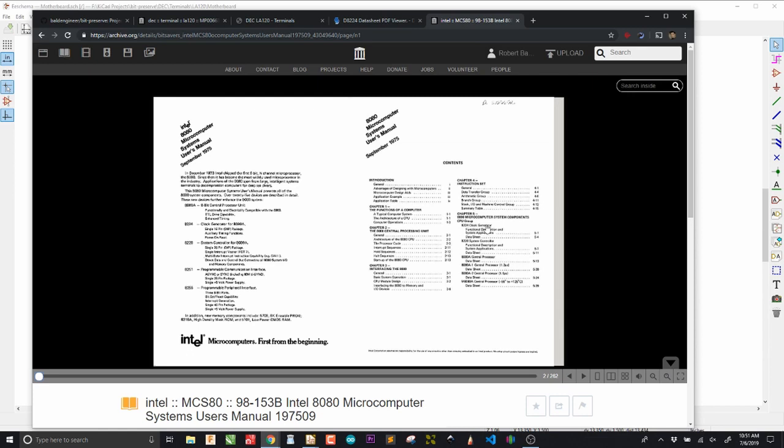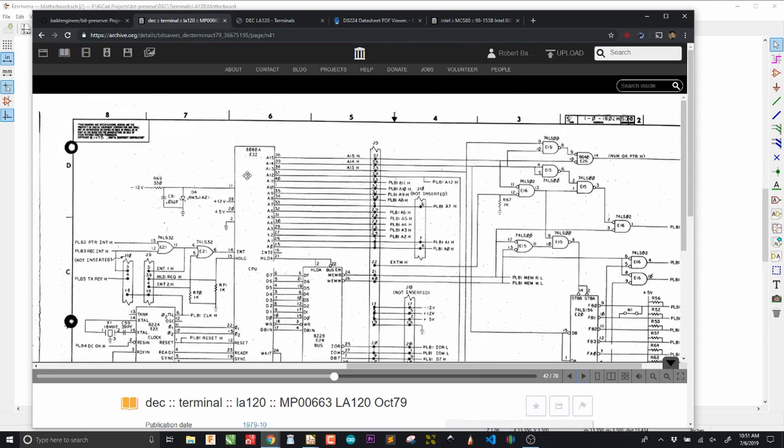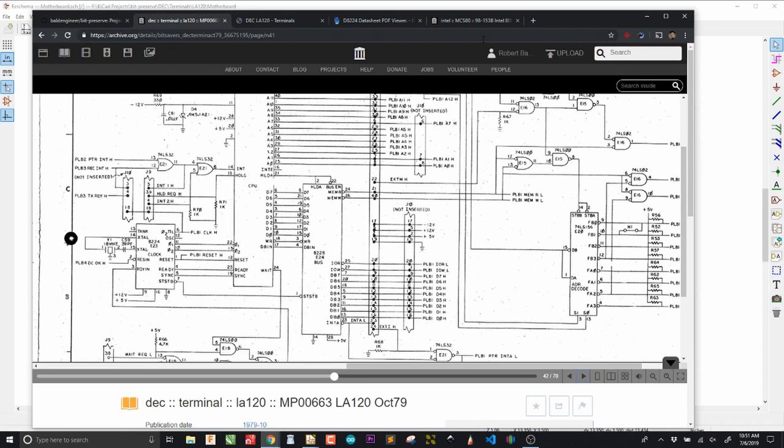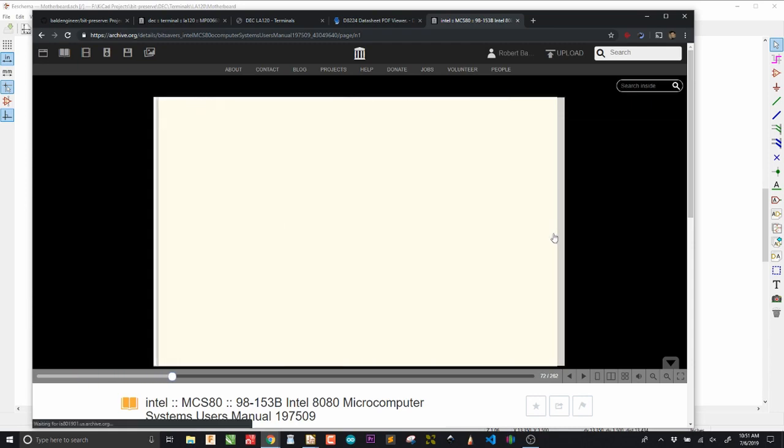8224 clock generator. Now the reason that I was able to do this, of course, is that I know that the 8224 is an Intel part specifically for the 8080 system. And if you look at the schematic, you can see right here the CPU is an 8080, so it's part of that system. As well, there's going to be this 8228, which I believe is another Intel part, which is right down here. So anyway, what we do is we go to the datasheet, so it's page 5-1.